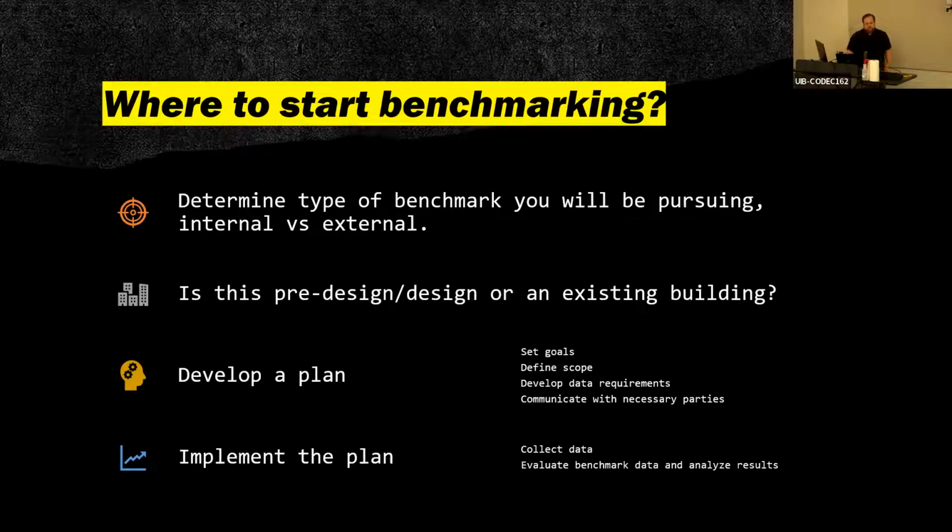But let's talk about where to start for benchmarking. So, an overview: you need to determine the type of benchmarking you will be pursuing, either internal or external. Is this a pre-design or an existing building? That's going to affect the software and the type and amount of data you're going to need to collect. Develop a plan. You want to set goals, define scope, develop data requirements, and communicate with necessary parties. And then, of course, the most important part, implementing the plan: collecting data, doing a site visit, analyzing that data, and evaluating the benchmark data and results.